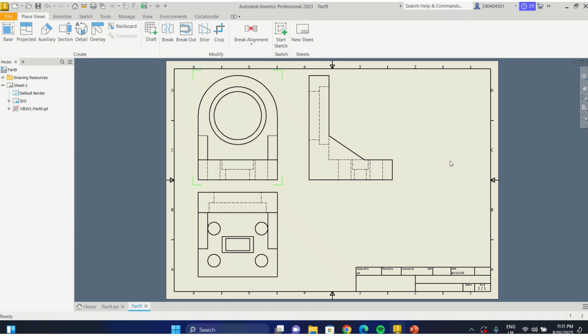Now, another thing that is important to your drawing before I talk of dimension is what we call your center lines. Center lines are needed where you have circles, and also at places where you have some symmetrical objects like symmetrical squares or symmetrical rectangles.